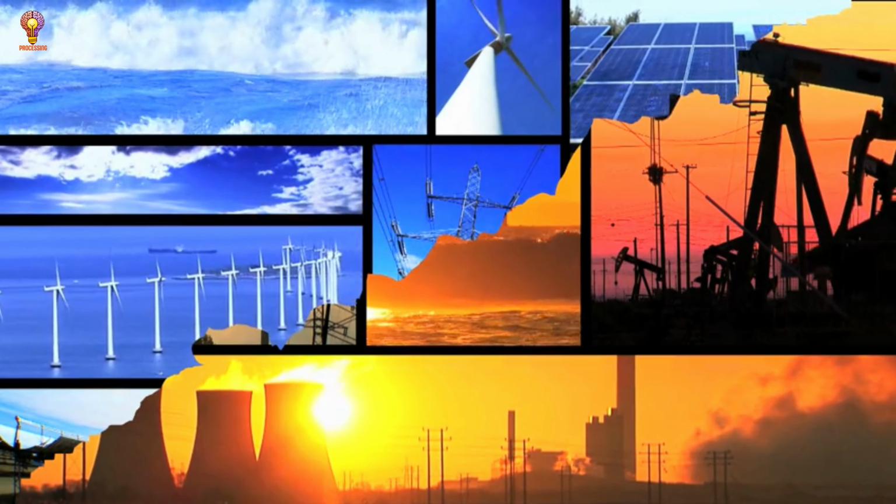Concentrated solar power, CSP process. Sunlight concentration. Mirrors focus sunlight onto a central tower or solar troughs. Heat is used to boil a fluid, molten salt or water, to produce steam. Turbine and generator. The steam drives a turbine, generating electricity. Energy storage: CSP systems store heat in molten salt tanks for electricity generation at night.